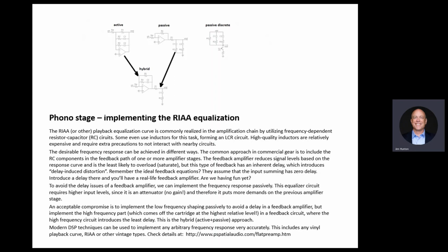If you put the frequency shaping components after that stage, like we're showing here, that's a passive filter. The load is shaping the frequency response, and you can come up with a scheme where you're using both. Some of the frequency response is shaped in the feedback, and some of it is a passive component. So that's the first part, and it took the whole session.